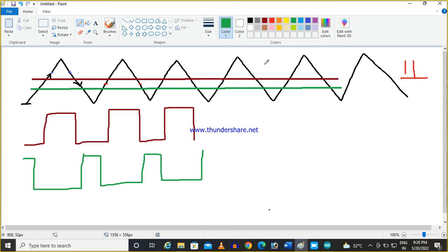Now you recall I told about the dead time in the last lecture, when there should be some gap between the two complementary pulse transitions. Now you see, I am getting that period, this time. Here both the pulses are 0. Both the pulses are 0. So I am able to generate the dead time. And how to calculate how much the dead time will be, I will explain to you.